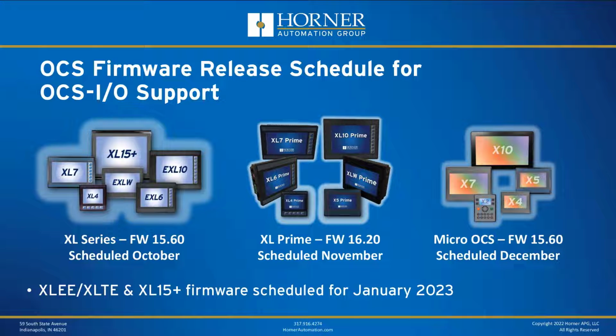How do you set the node ID of any given base unit? It's a good question, because as far as all of our other traditional CAN systems, they require it. Now, OCS-IO does not. You basically will assign a node ID within the software, but it works as a smart system using what is called a UUID, which is just a unique ID for the network, only used by OCS-IO. If you have a singular base, it goes out, searches for what IDs are on the network, and then automatically assigns that to base 1 and is up and running.